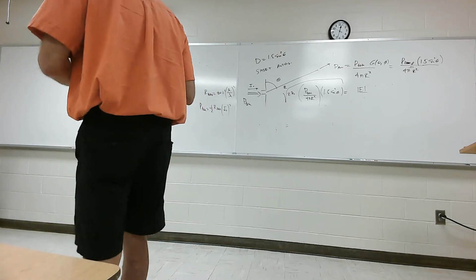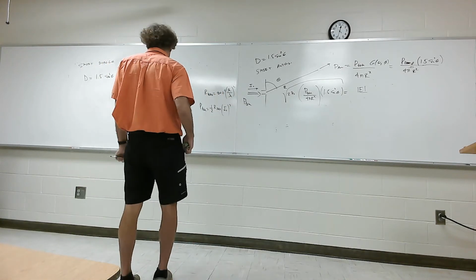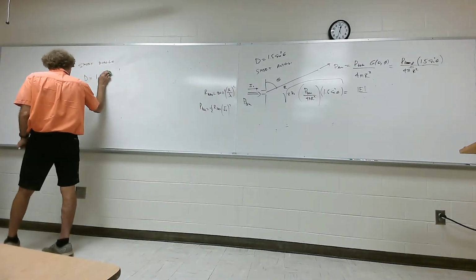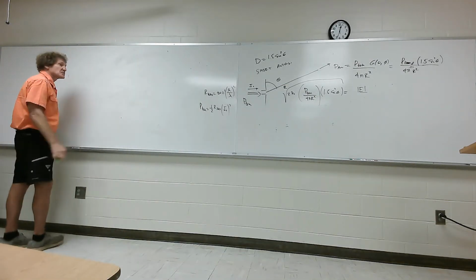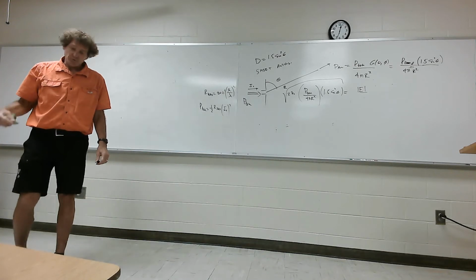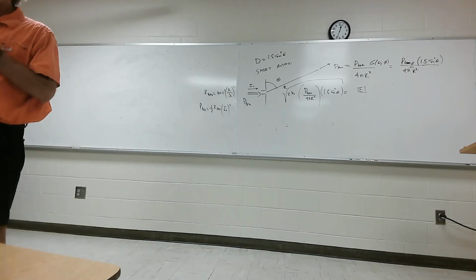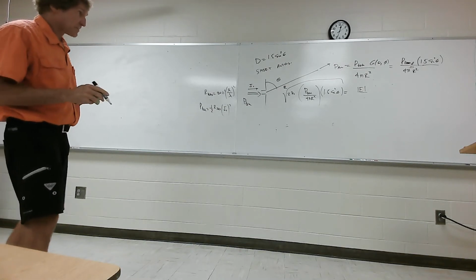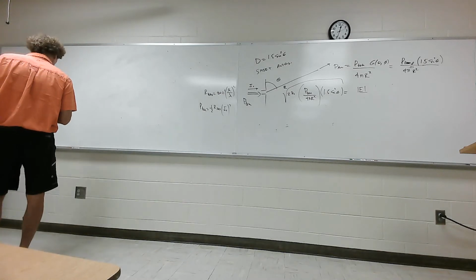Now, one other thing I want to do before I jump off of this short dipole. The 1.5, by the way, is the maximum gain for any small antenna. So you'll see these small loop antennas, anything like that that has a small feature size relative to wavelength. But I gotta mention one other thing.